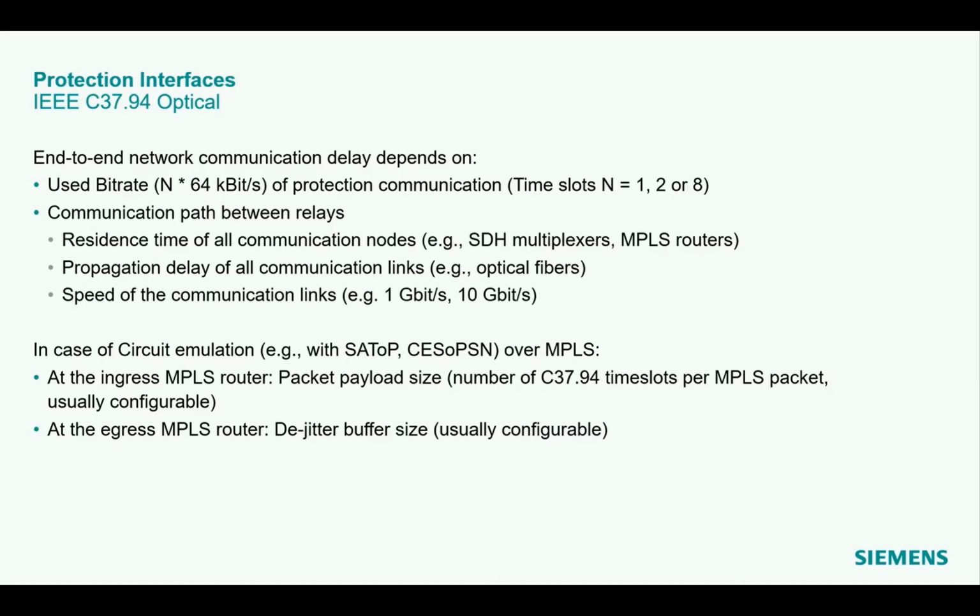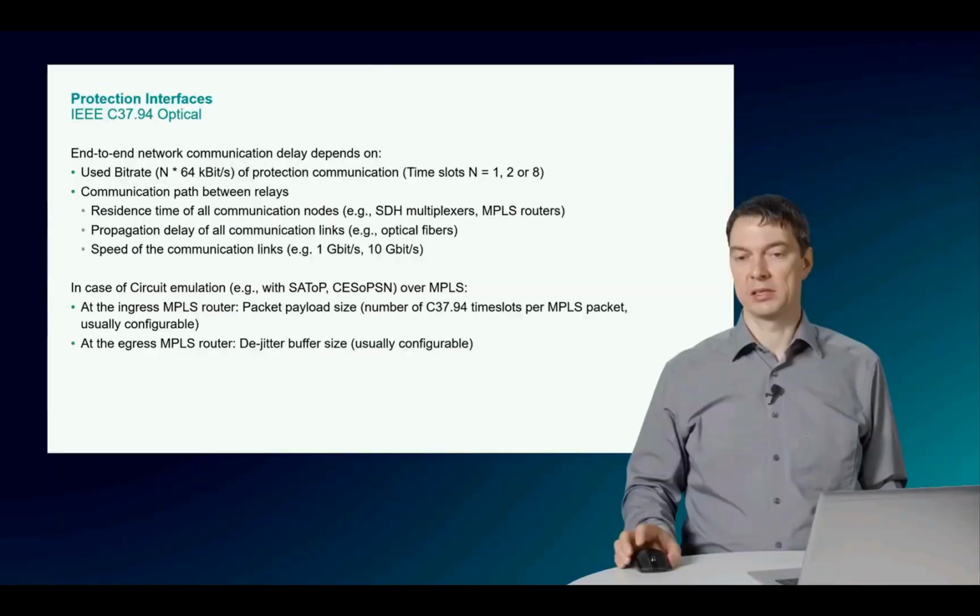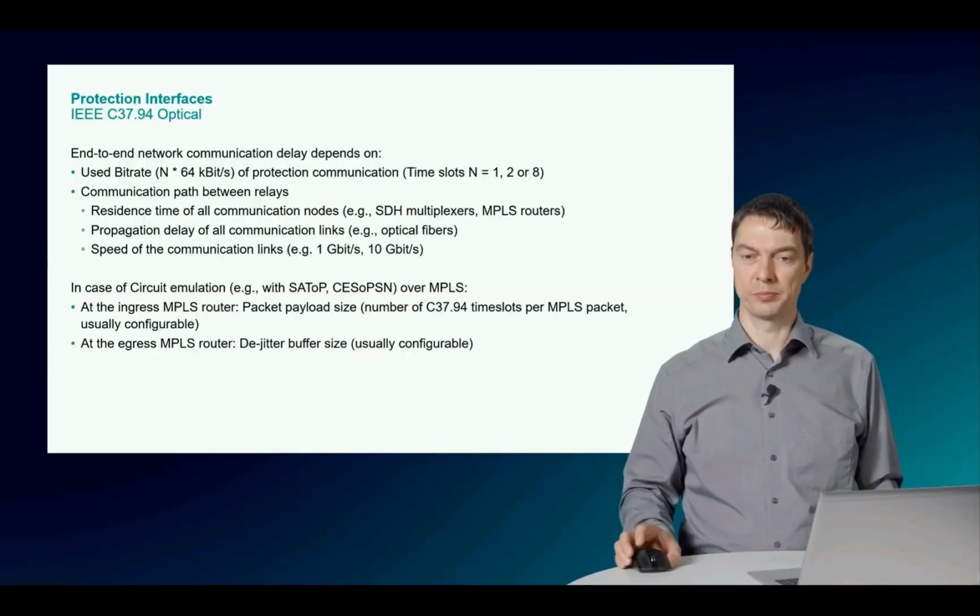In case of circuit emulation, that means using SAToP or CESoPSN over MPLS, the time also depends on the ingress MPLS router, particularly on the packet payload size, which needs to be packed into MPLS packets and is usually configurable, and also on the egress MPLS router. Here it's particularly the jitter buffer size, which is also configurable.